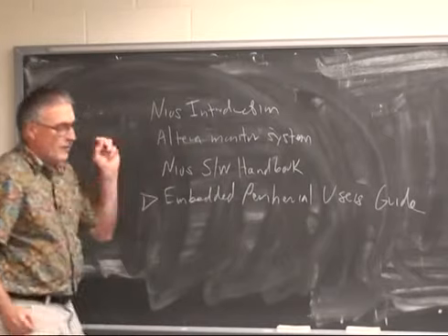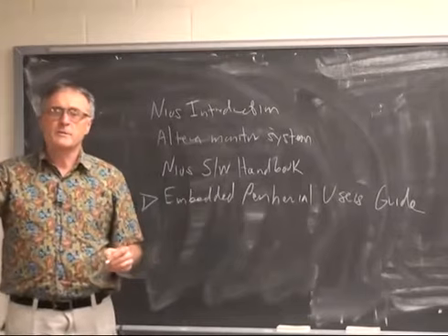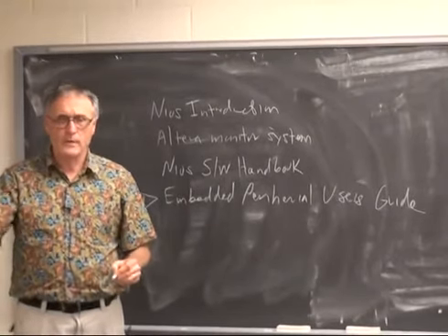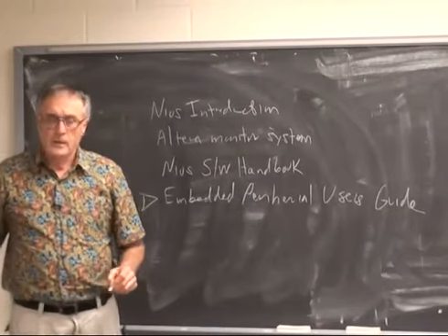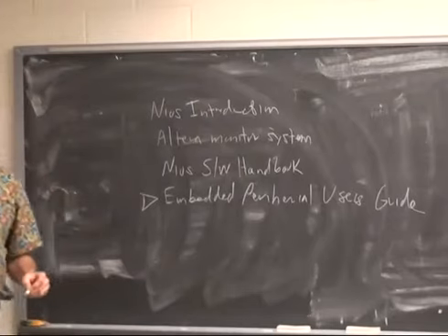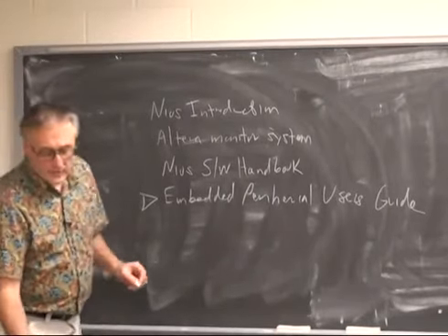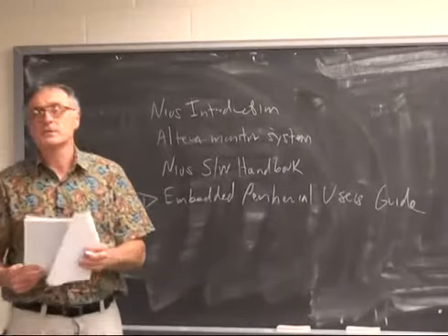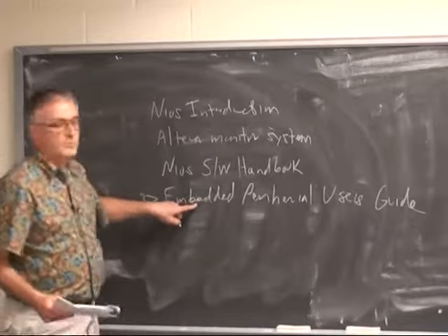This has all of the details about timer layouts, parallel I/O port layouts, SPI connection, UART, and what every bit in every register means. So when you're trying to define a timer and turn on a timer and set up an interrupt on the timer, for instance, this is the book you need to read.